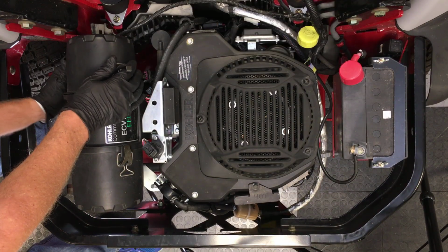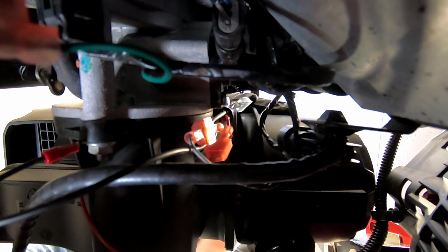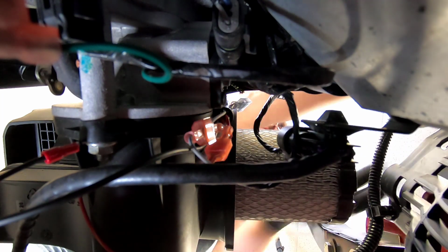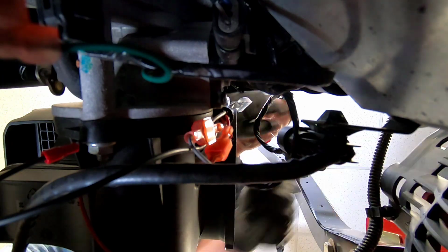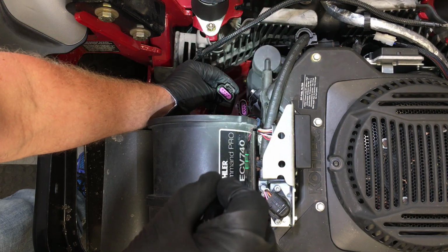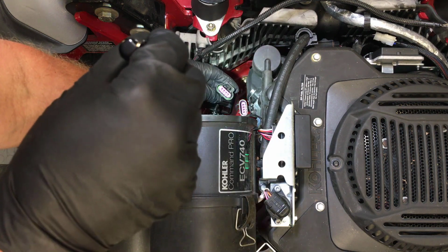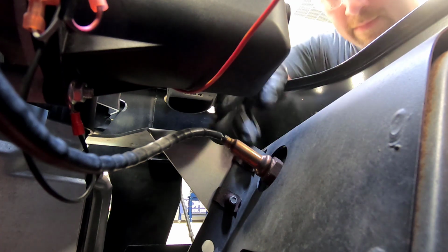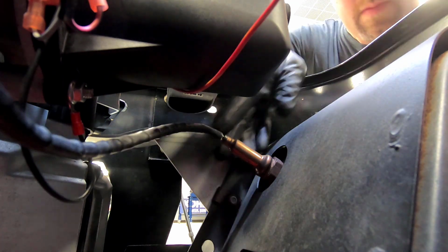Like any repair, it's best to start with a visual inspection. Disconnect the sensor connector and inspect terminals for signs of damage, specifically corrosion. Inspect for wiring damage like melting or incorrect routing that pulls the wires too tight.